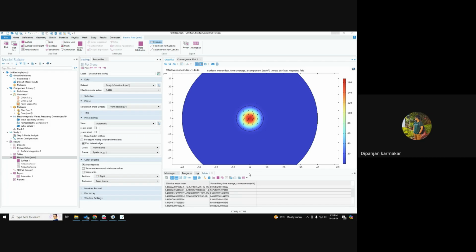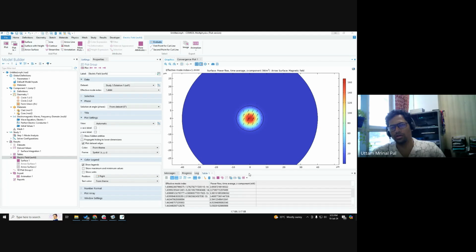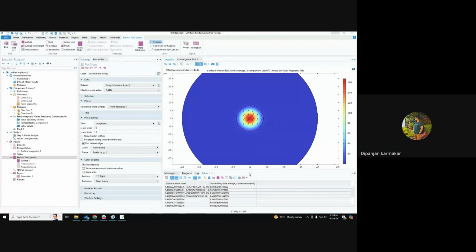The core section has the same refractive index, but the central core region has ytterbium along with silica, and the outer section of the core has aluminum, so it is passive. They amplify the first order mode, that is the fundamental mode, as it is Gaussian shaped, and the higher order modes do not get amplified. Using that, they suppress the higher order modes.